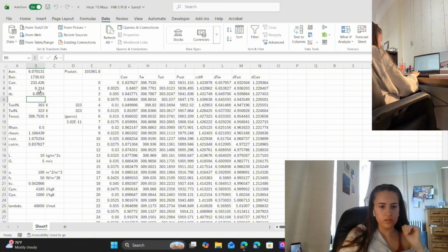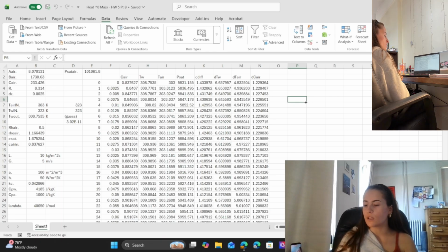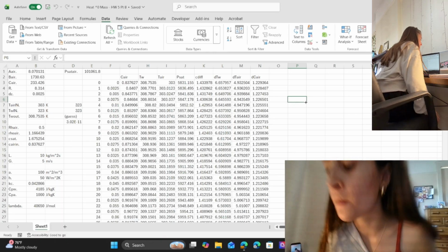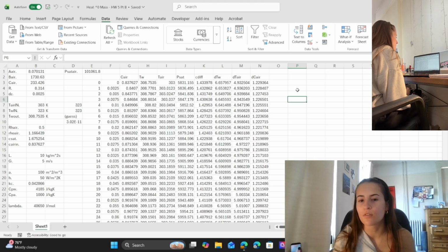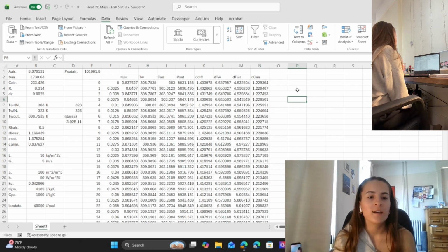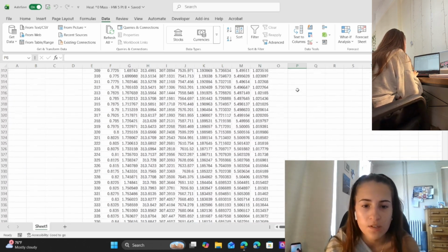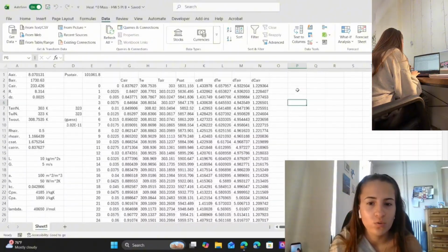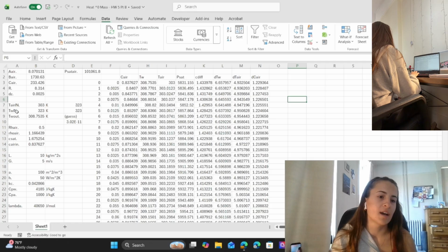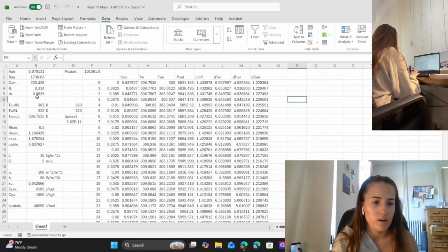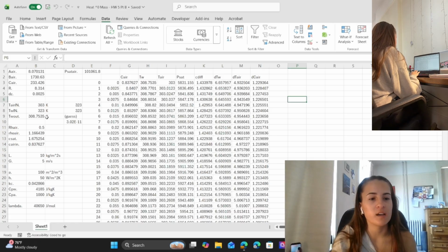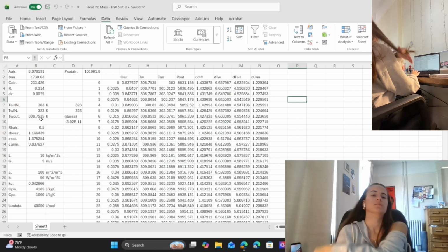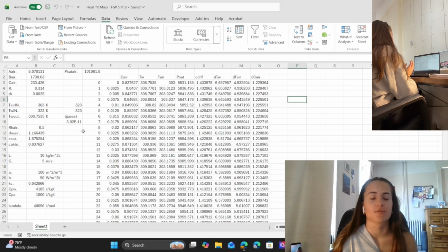So then, yeah, that's kind of showing everything that I wanted to show today with this video. So we derived all of these equations here for change in temperature of the water, air, and the concentration of the water within the air. And we've modeled it in Excel to kind of show how these numbers are changing as you go through this cooling tower, and also showed the effect of changing the length of the tower, as well as how that temperature is changing when we guessed it versus what it actually is.